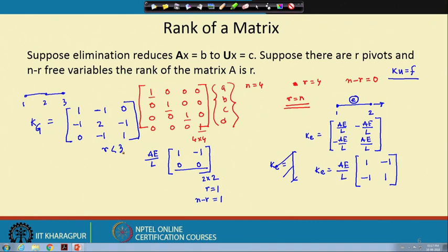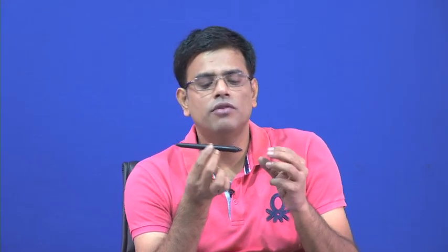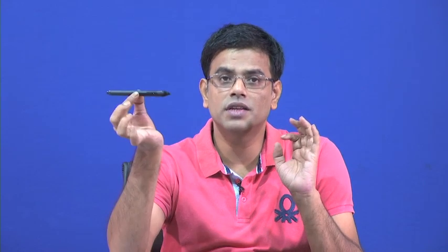So, this has a very physical significance because you see here, if I have a truss element here, now if I do not put some constraint to the truss element, it can go anywhere. Suppose if I do not put any constraint to this truss element, it can go from here to here. So, there is no deformation in the truss element, it is just translation.